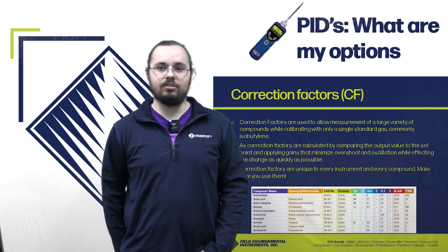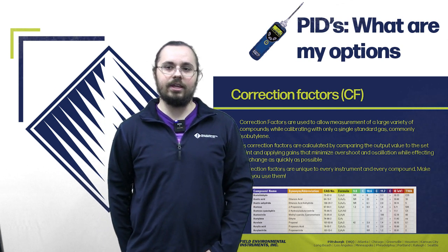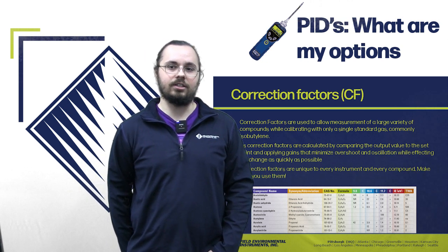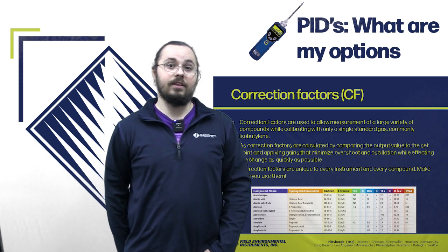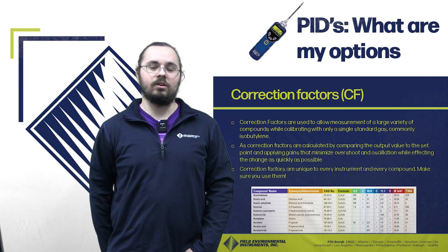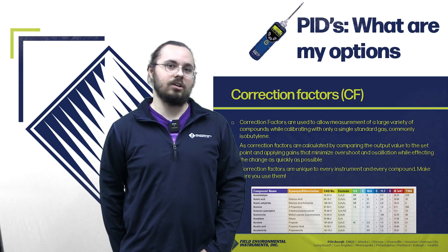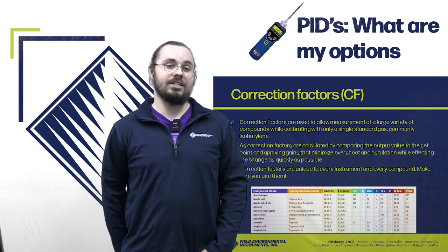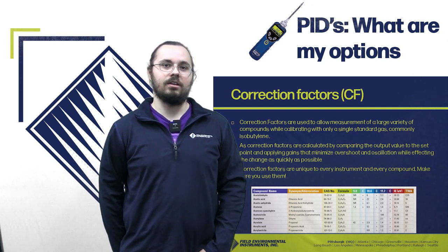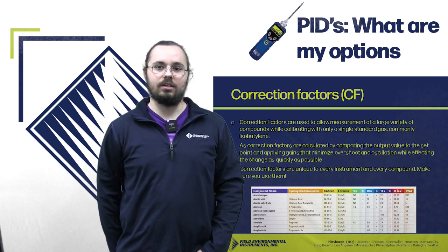Correction factors are calculated by comparing the output value to the set point and applying gains that minimize overshoot and oscillation while affecting the change as quickly as possible. This essentially gives you a value which is then multiplied by your calibration gas correction value to give you the value of the actual gas being measured. The main reason isobutylene is used as the calibration gas is because its correction factor is 1, giving it an easy time to make that equation.